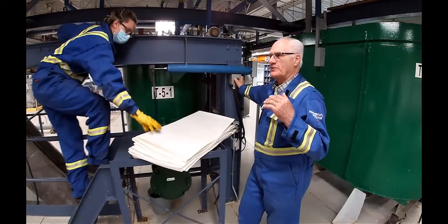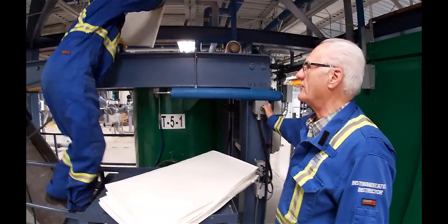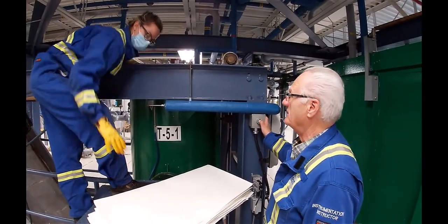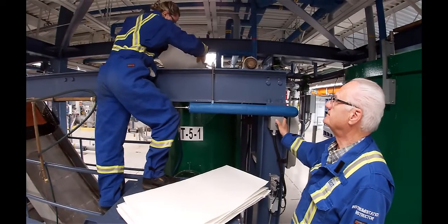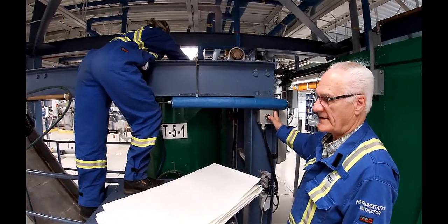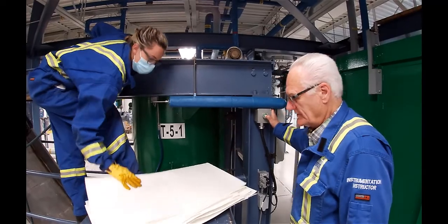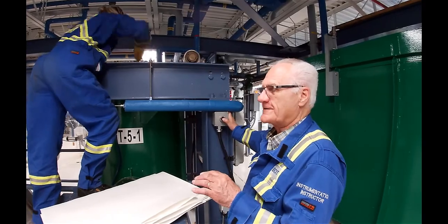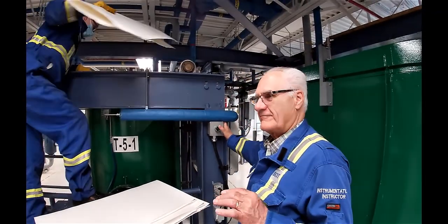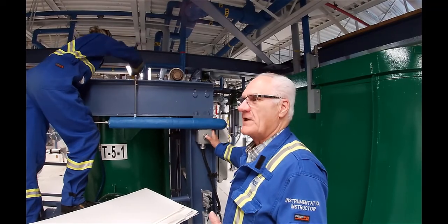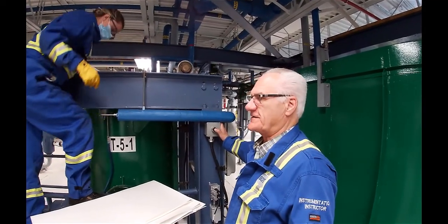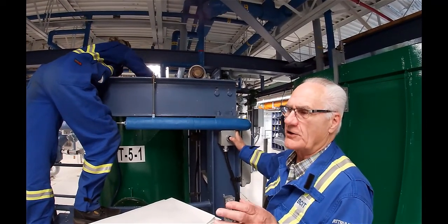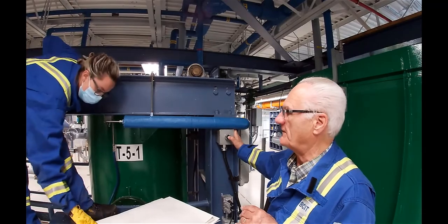As Mari begins to load in the sheets later, they're going to get harder and harder to get in there. Begins to get a lot of stock in the slurry. When we talk about consistency, it's the amount of fiber in the slurry. So a tree naturally standing in the field would have 50% consistency because it's 50% water and 50% cellulose fiber and tar and lignin that's holding the fiber together.